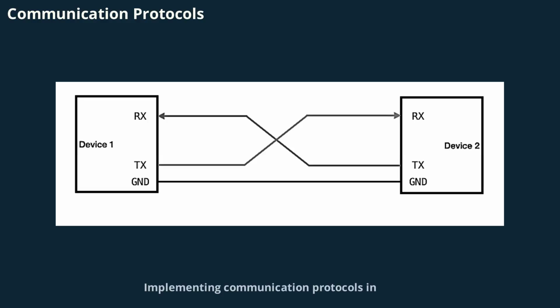Implementing communication protocols in firmware involves managing state machines, data buffers, error detection, and timing constraints. Each protocol, UART, SPI, I2C, and CAN, has its own complexity and typical applications. For example, UART is often used for debugging or Bluetooth modules, while SPI is common for sensors and displays. Understanding protocol requirements helps you design robust and efficient communication systems.